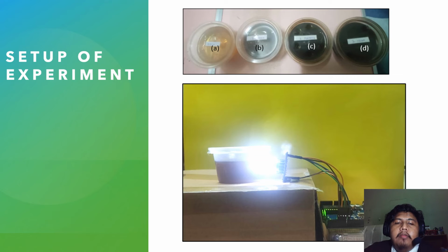The output of the system is the RGB, which is red, green, blue value. The RGB value of the color is represented by a 3-part, 2-digit base hexadecimal value ranging from 00 to FF. But in this experiment, the RGB value will be analyzed in decimal value ranging from 0 to 255. The number 0 indicates no representation of the color, while the number 255 denotes the highest possible concentration of the color. The RGB value resulting from the optical sensor reading for all samples will be corrected with EV lux for further analysis.